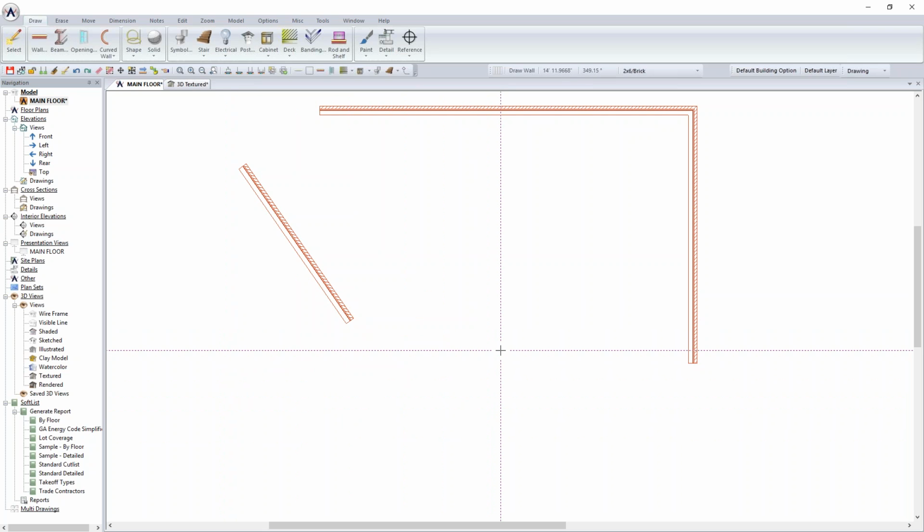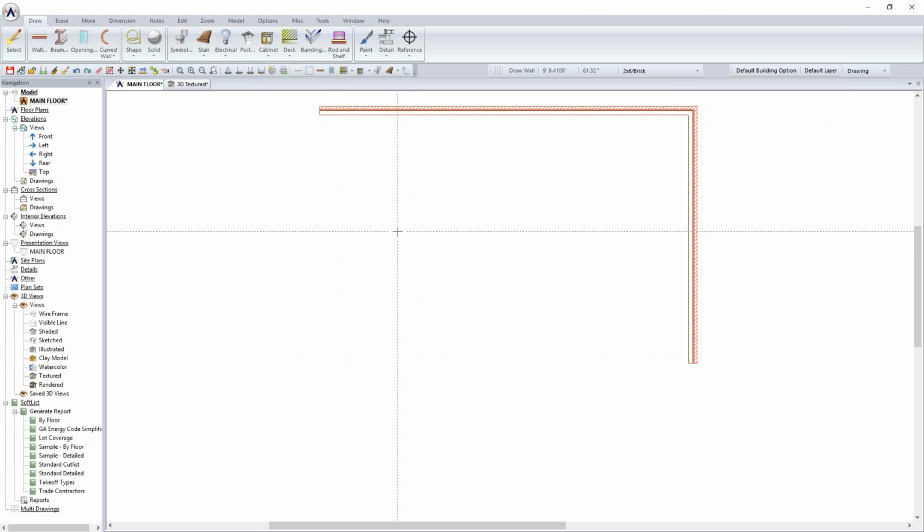You put something in and you determine that you want to remove that. And so in addition to drawing, one of the things that you will use a lot of is the undo command. Now you can see that my cursor is hovering over the little blue arrow pointing back towards the left side of the screen, and it tells me undo wall. And it's basically pulling down what it's about to do. And if I click that icon, it's going to remove the previous item that I drew.